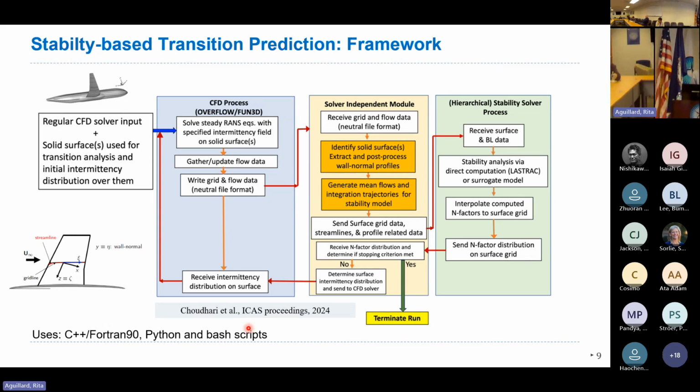So the intermittency function is defined on the surface, right? Yes. For any point in the volume, you base it on the distance function. And you do it for every point, not only within the boundary layer, even if the distance is very big. That's one approach which we can still refine. Right now, because it's a surface-intermittency-based approach, we are assuming that every point in the volume uses the same intermittency as its associated wall-normal point. That may not be completely correct in a lot of cases, but unfortunately the current CFD solvers are built to take in that particular parameter. We do have the ability to change that and give a more volume-based intermittency, but the stability analysis itself will still only be able to give you results based on a surface.